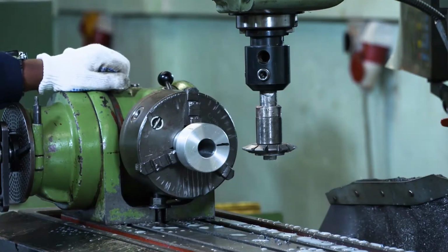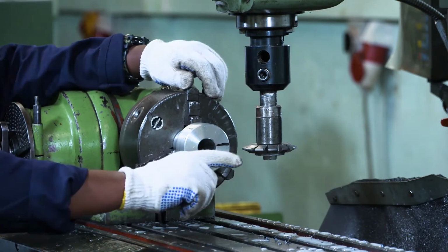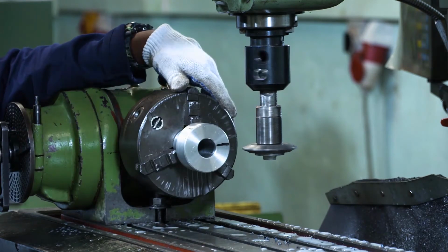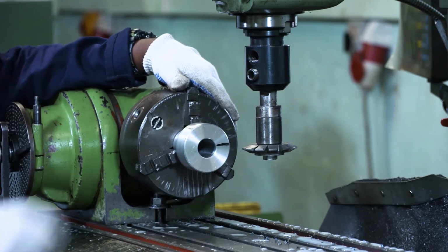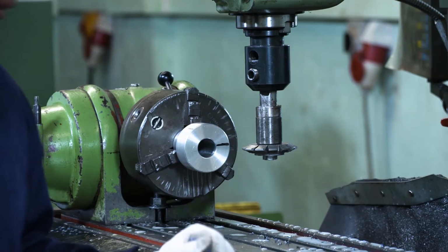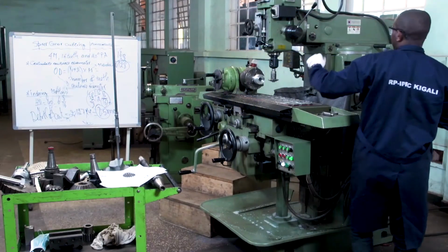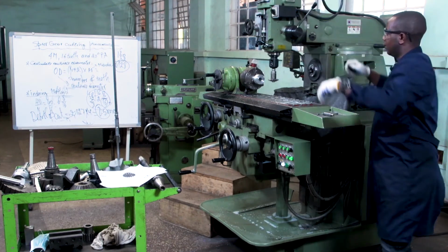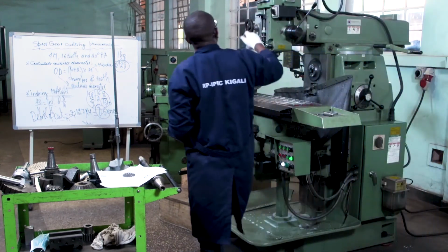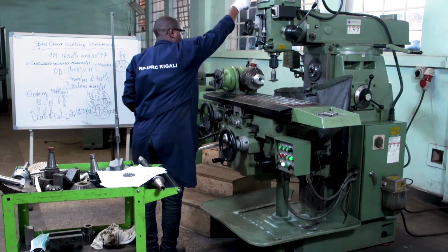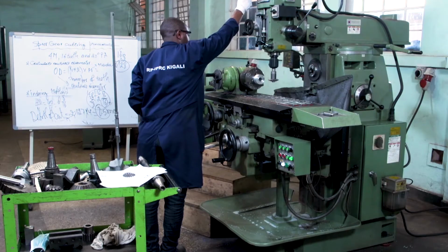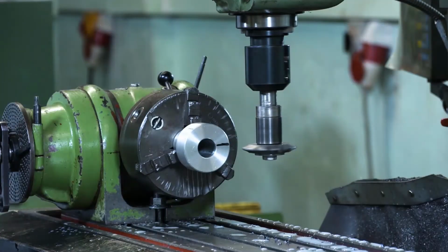Now we can choose the direction of cutting. Because this milling cutter has the clockwise direction, you have to choose this direction. But you have to reduce the speed. Okay. Good. So now we have